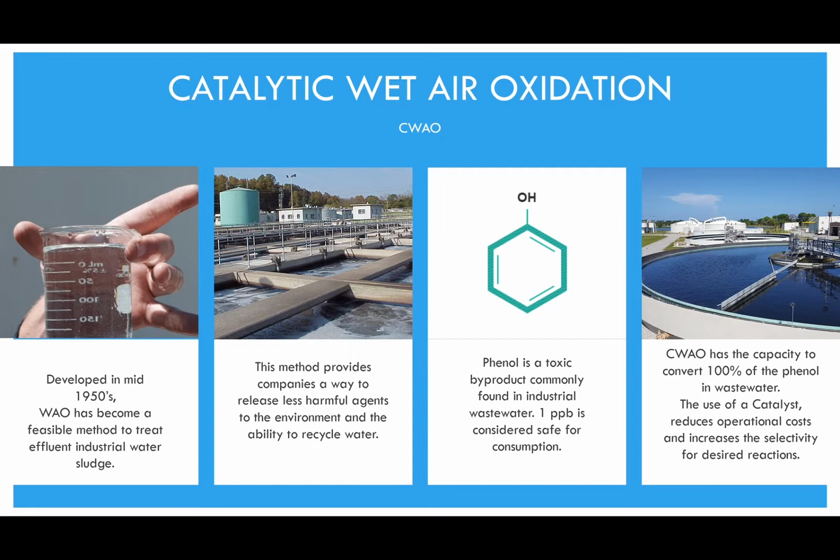Phenol is a toxic byproduct commonly found in industrial wastewater. 1 part per billion is considered safe for consumption. Catalytic wet air oxidation has the capacity to convert 100% of the phenol in wastewater. The use of a catalyst reduces operational costs and increases the selectivity for desired reactions.